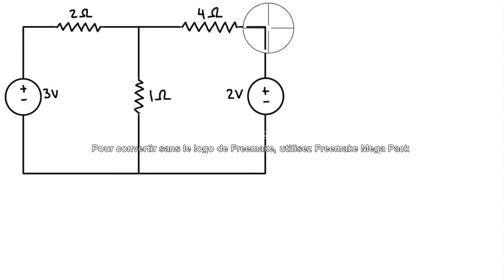And what we want to do in nodal analysis is pick one node to ground it. It's not really a real ground, but it's just the reference that we're going to take as 0 volts for all of the other voltages. And in cases with voltage sources, especially more than one voltage source, if you can ground the node that's connected to one or more than one voltage source, that's going to be a good one for us to take as reference. So let's draw on a ground here. So this node is going to become our 0 voltage for the rest of the problem.